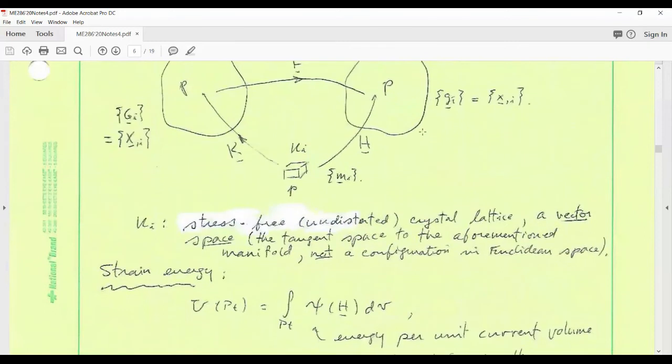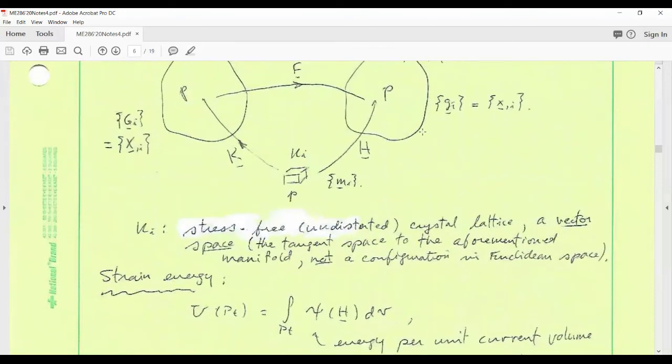Now for our whole analysis, we'll just take into consideration the deformation we had before due to plasticity, and now we just load the specimen again elastically. Are we going to analyze what's happening if we surpass again the elastic regime? Of course, that's the whole aim of plasticity. So this H will induce an elastic strain. You'll be straining the lattice. That means we'll be stressing the lattice. And if we stress it too much, the material will yield.